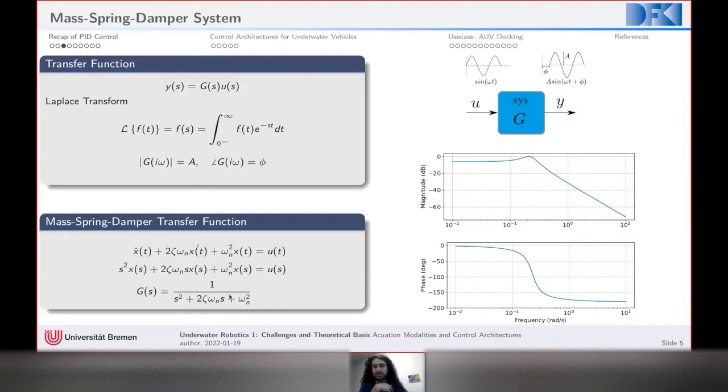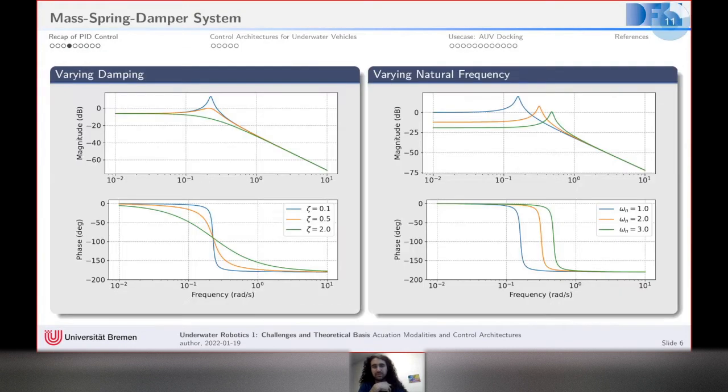And the more damping I give, the more I'm going to slow down this peak, or get rid of it. You can see it if you simulate that system and play around a little bit with damping, just solving this differential equation and doing this Bode plot. Here the blue represents very low damping in the system, so you can see how the peak is really high. When I start adding damping, you can see how this peak is getting tamed, reaching a nice and smooth curve.